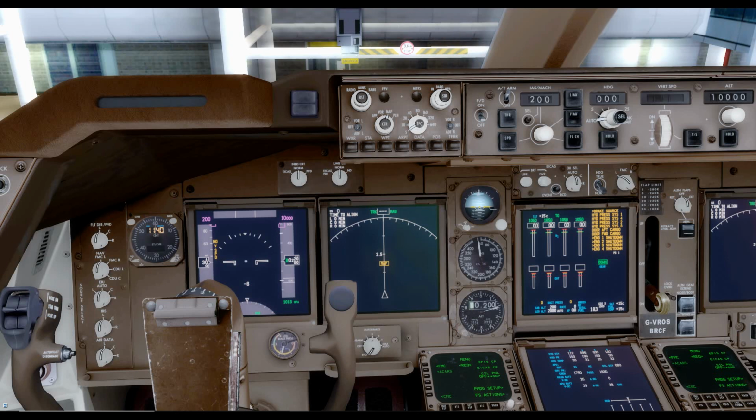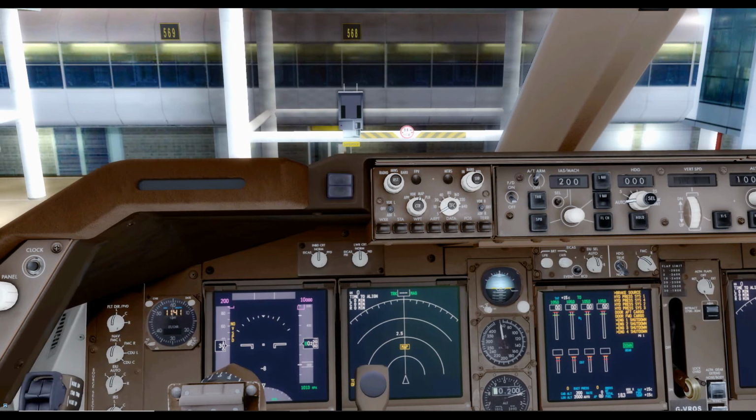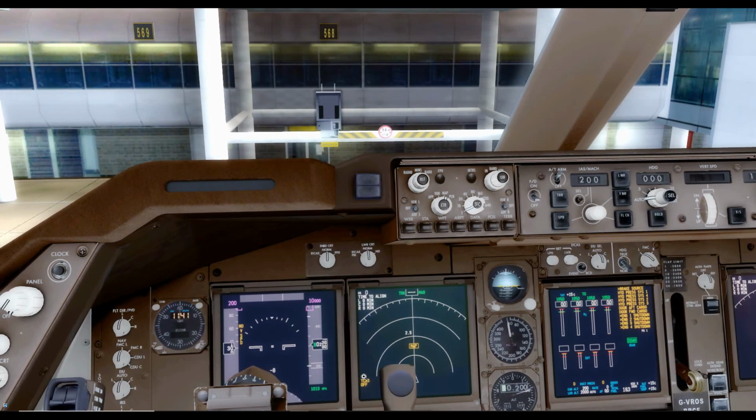If you're operating an aircraft with the ISFD, the digital combined standby instrument, rather than these analog standby instruments, then you should be checking that there are no flags or messages in the ISFD. The EFIS control panel could be set really according to preference. We will need the TCAS display showing, and you'll notice that this brings up a TCAS off flag on the navigation display, which is normal at this stage. The transponder is currently in standby.